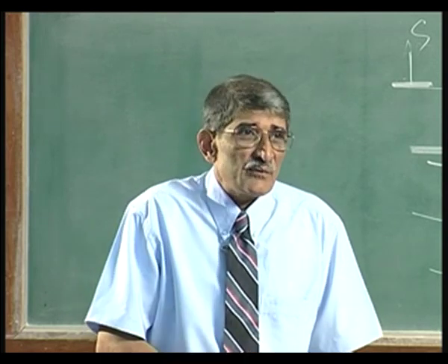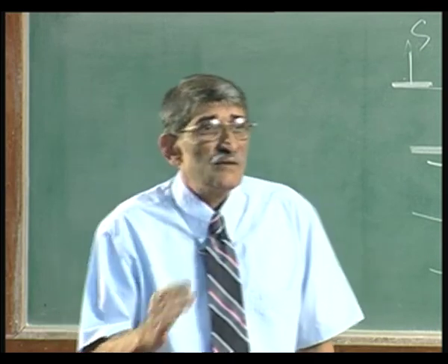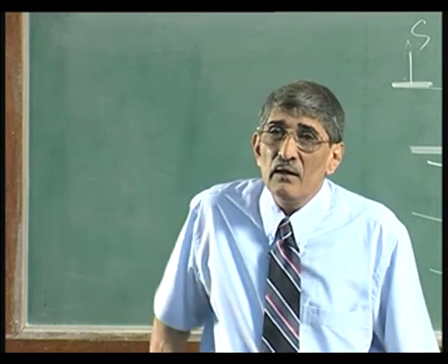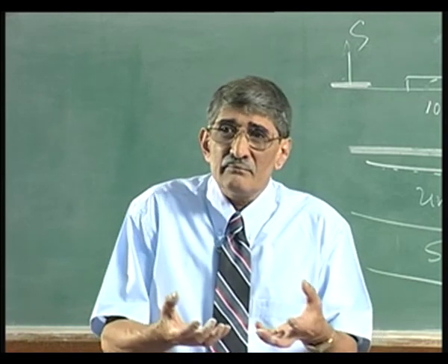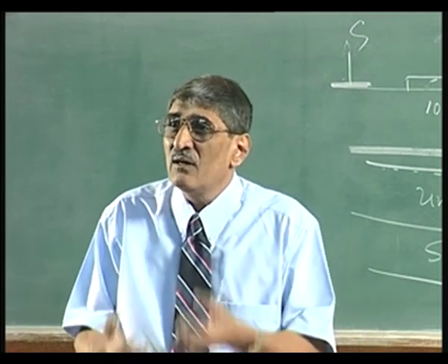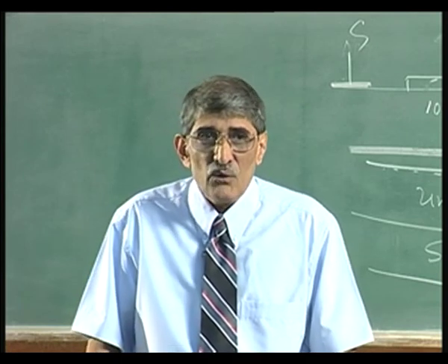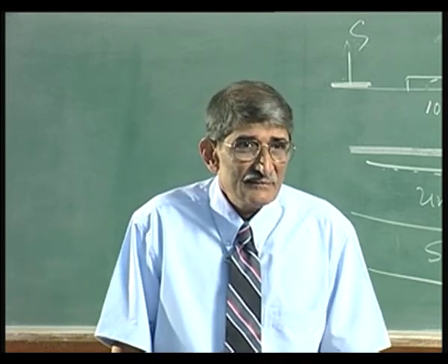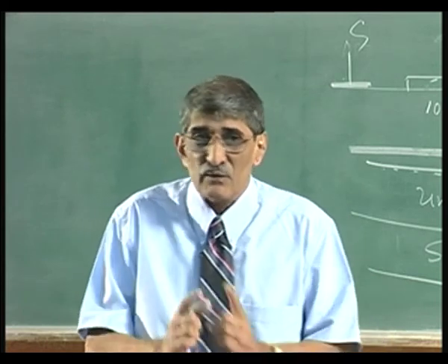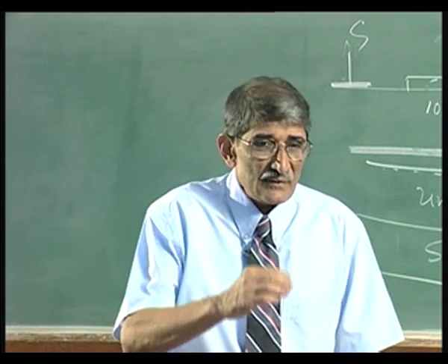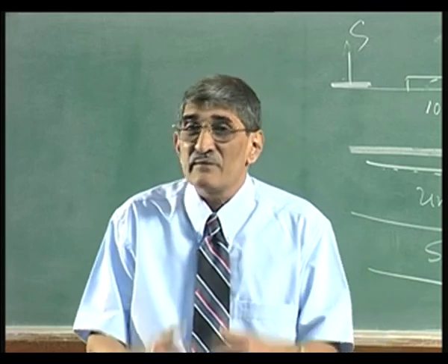Now, what are you worried about? I will take up detailed discussion next time, but I will just tell you what is going to be the thing here. You are worried about realizing an epitaxial layer of gallium indium arsenide on gallium arsenide, because of lattice mismatch. What happens if there is lattice mismatch? If you can tolerate that lattice mismatch, if there are no defects generated during that growth, then you can put gallium indium arsenide on gallium arsenide. So, the gallium indium arsenide channel layer will give high mobility.